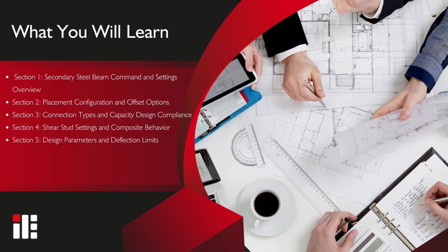In this video, we'll focus on modeling secondary steel beams in ideCAD Structural. You'll learn how to use the secondary steel beam command and adjust key settings such as alignment, offset values, and placement configuration. We'll also cover how to assign connection types that comply with capacity design principles, ensuring safe and code-based